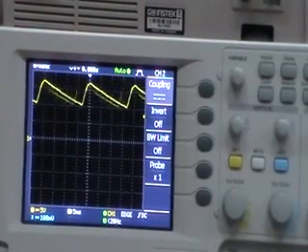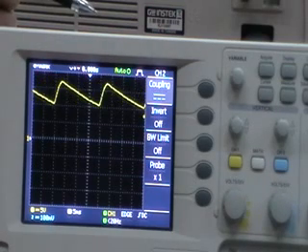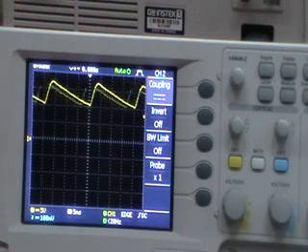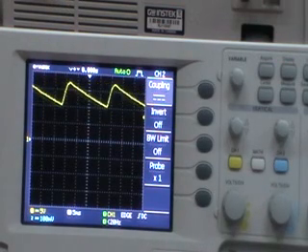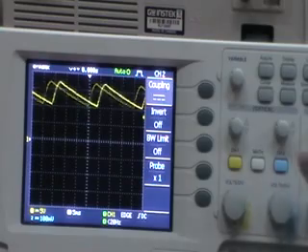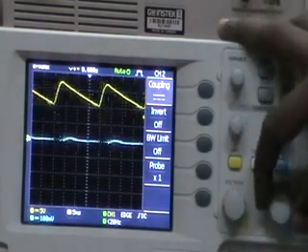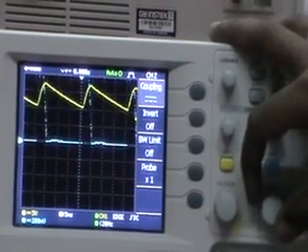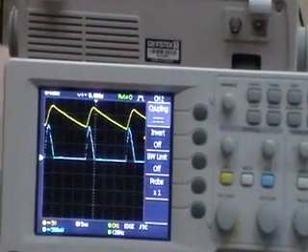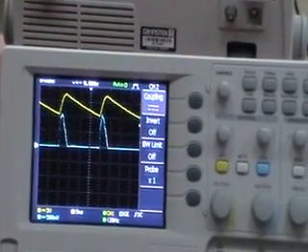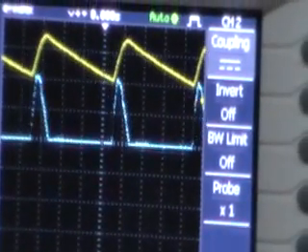The other thing that we have to find is the diode current waveforms by using the channel interconnections. So these are the waveforms. This is the diode current waveform, and we can find the peak value of the diode current easily from the diagram observed in the DSO.